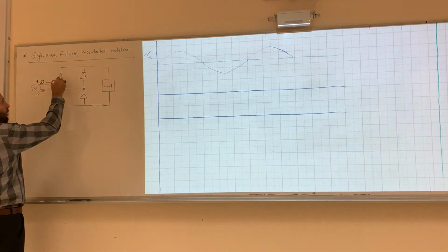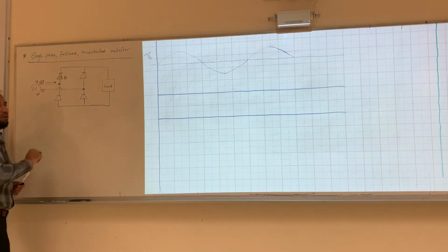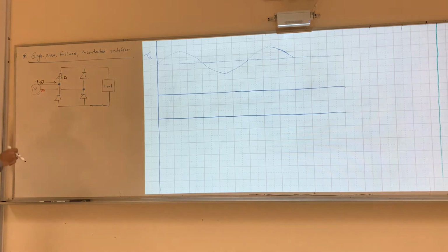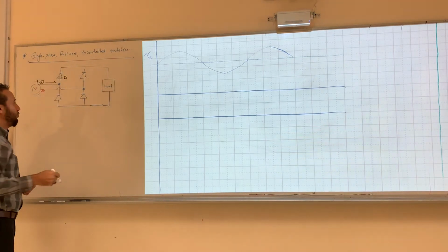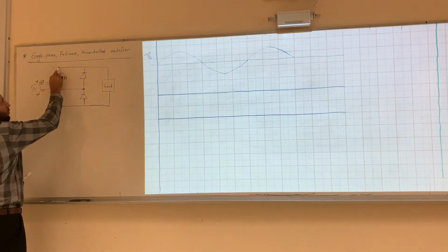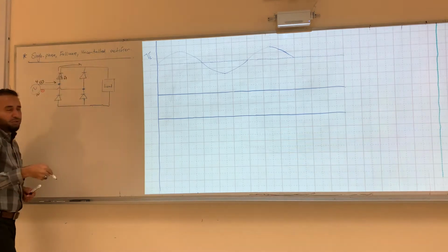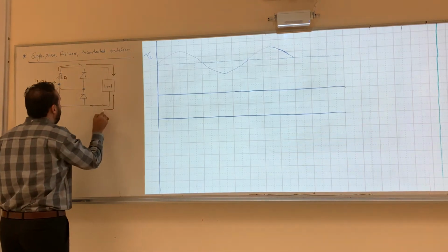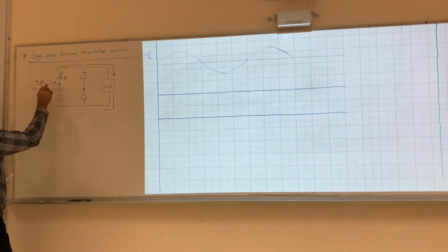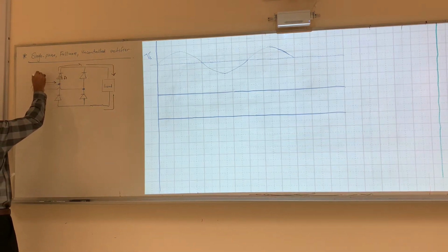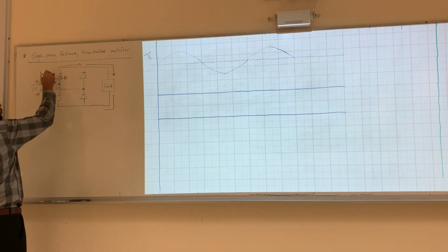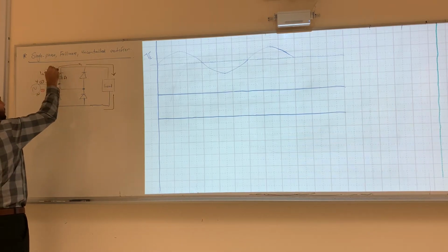So this one here will be power diode number 1, and this one cannot conduct, because the current cannot go from cathode to anode, it goes the opposite. So the current will come here, it cannot go this way, it will go through the load right here. So we can say here that I source is the same as I diode 1, the same as I out.